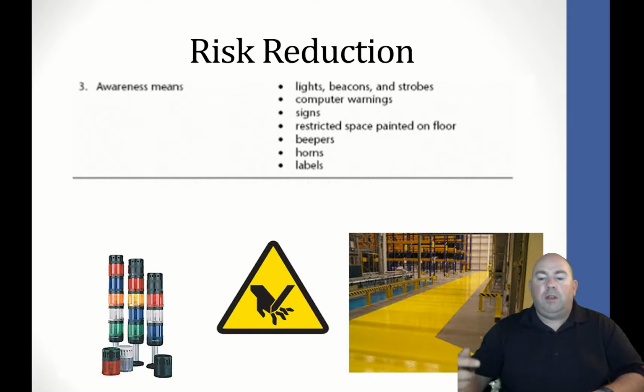Awareness means is things like using signage, using lights, using lines on the floor, things like that. Anything like that that basically gives you a visual or audio indication that there is a hazard present. Okay, this would be called awareness means. And this is a completely valid form of risk reduction as well.